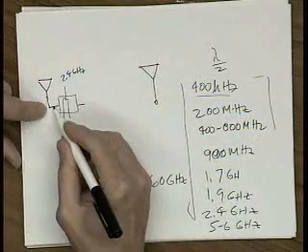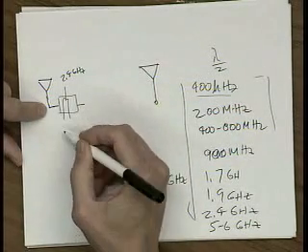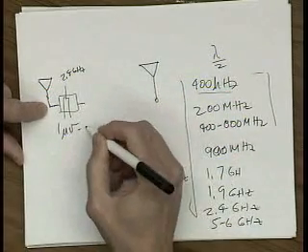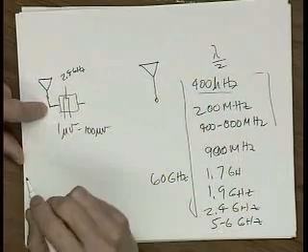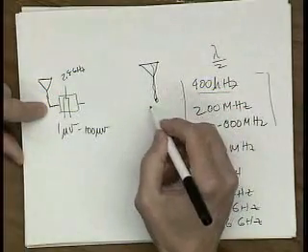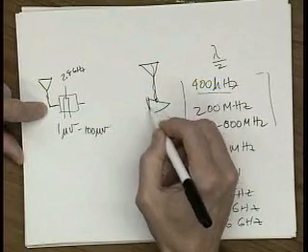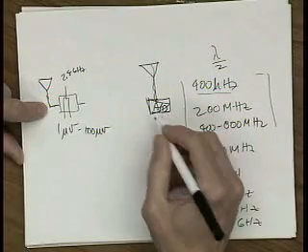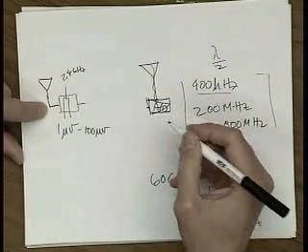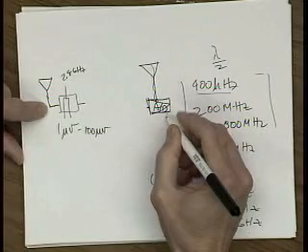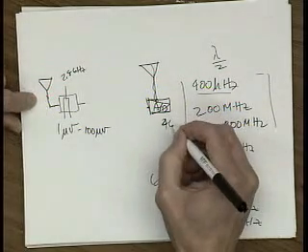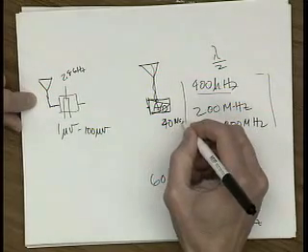The signal coming in at this point is really small, down at the microvolt level, maybe microvolts to hundreds of microvolts. What we're trying to get to is an A to D converter. For 802.11, it's probably running at 40 megasamples per second, 40 megahertz.